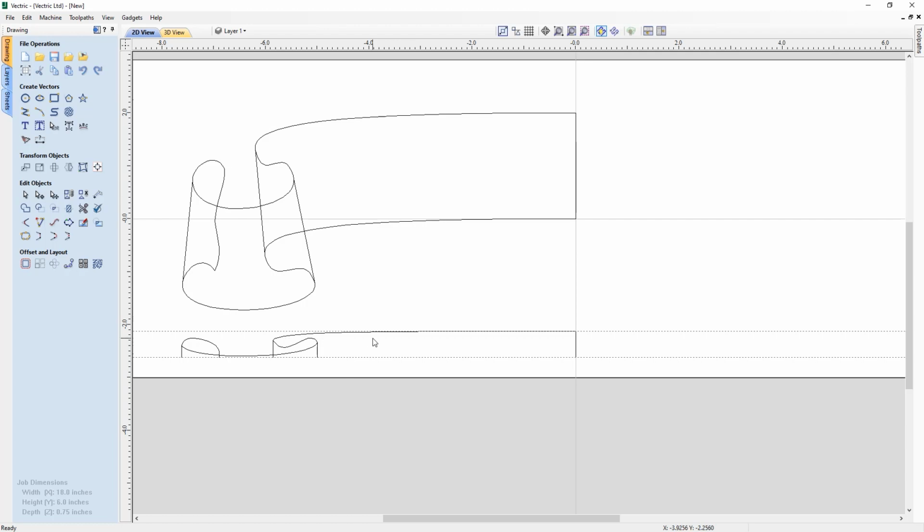Now, in order to do that, what we need to have is some drive rails. One thing that is important to note here is that all of these cross sections touch the modeling plane. They all have legs on the end, so they come from the same point. If you forget to put these legs on the end, then what will happen is it'll actually tilt down, so this node actually touches the modeling plane and it will look a little funny, not what you expect.